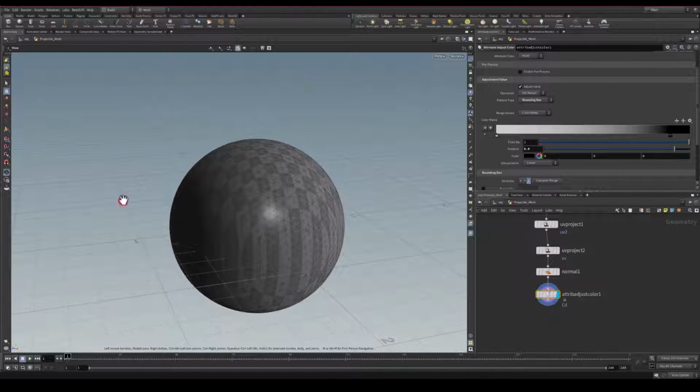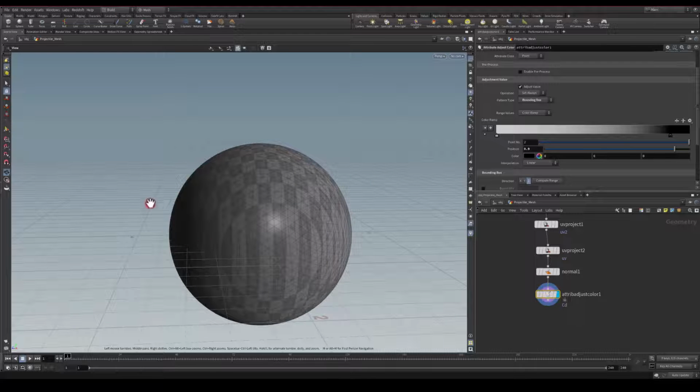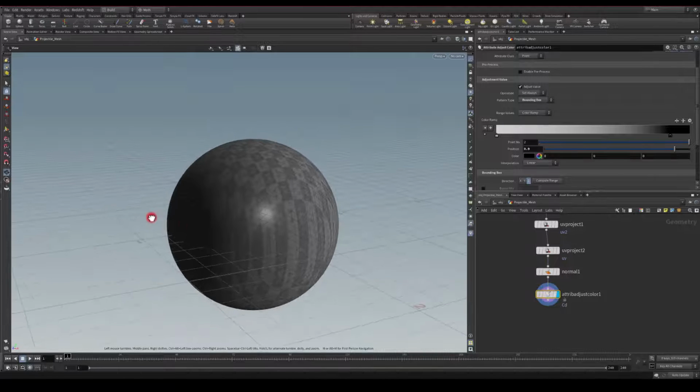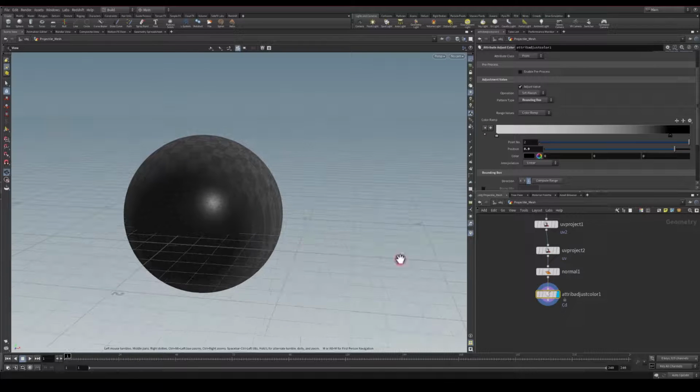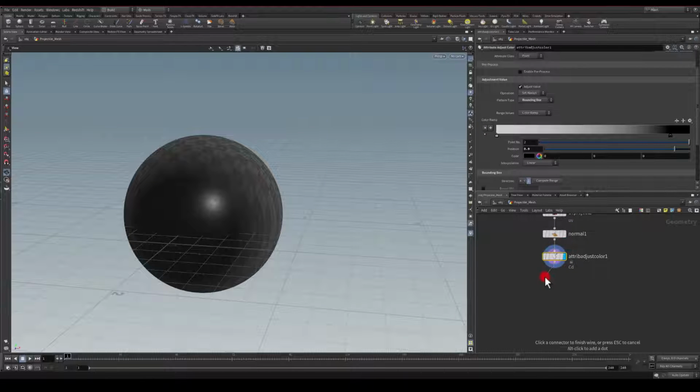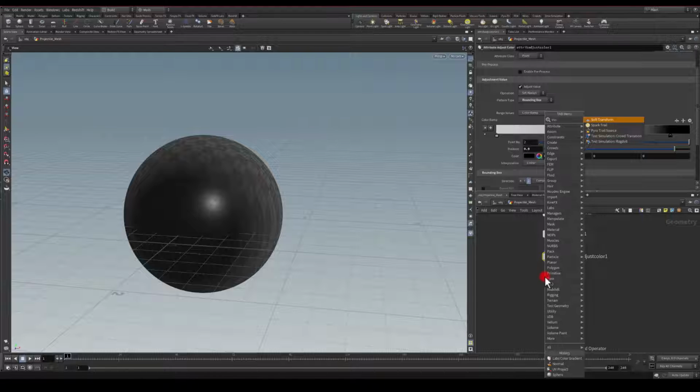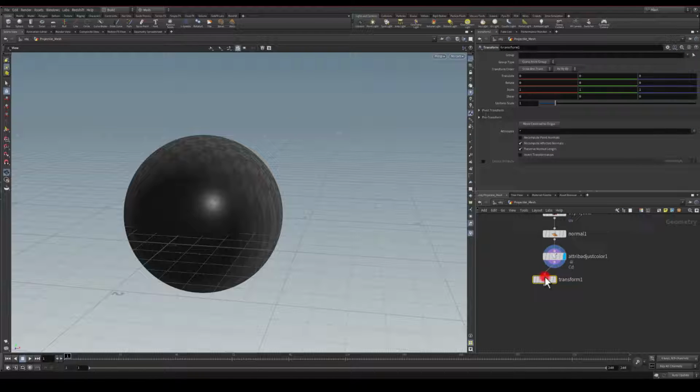And I think I'm gonna use this for the glow in the game engine. So I'm gonna mask my glow by vertex color and apply just a normal color, very intense emissive color to it. Last bit, I just wanna create a game engine scale, so transform, and I'm gonna multiply this by, let's go actually with 100.